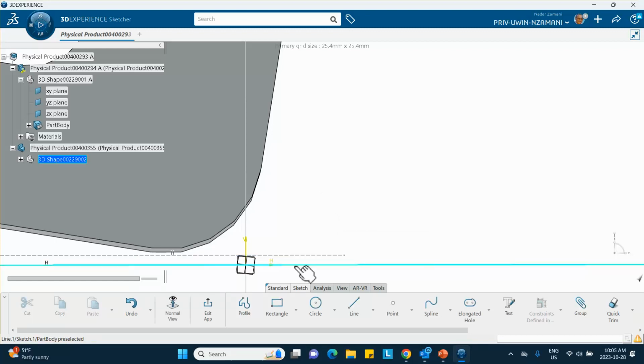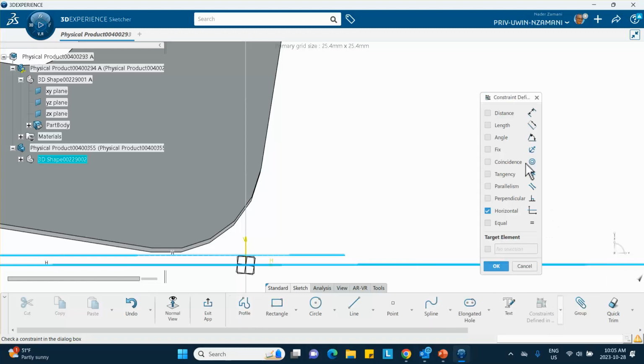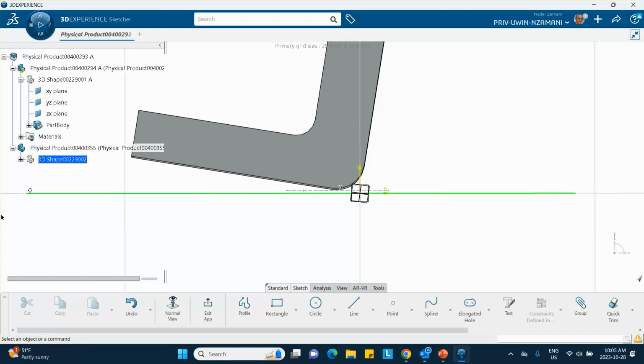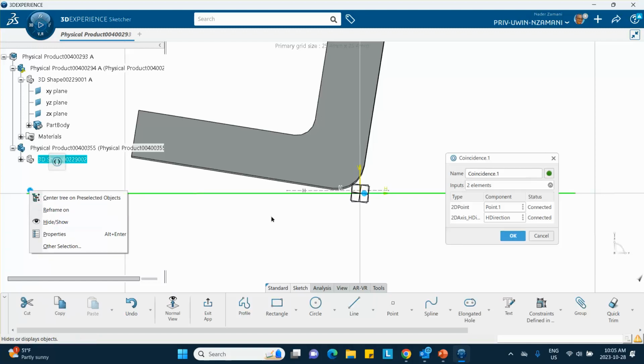It is construction. Now I say this line controls that line. Coincident. The only problem is there may have been some coincidence which won't let you do that. But let's see if I can make it coincident here. No, cancel. The reason is that when I drew this line, there is a coincidence here, so I have to delete it because it won't let this thing go. So you can delete it from here. Let's check it out. Can I delete it from here?